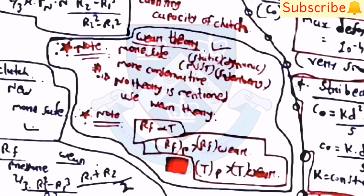Now there is a note there. The wear theory is the safer theory as well as the more conservative theory. So if no theory is mentioned in the examination, use the wear theory. And the other note is that Rf is proportional to T. Then Rf for uniform pressure is greater than Rf for uniform wear, as well as torque for uniform pressure is greater than torque for uniform wear theory.